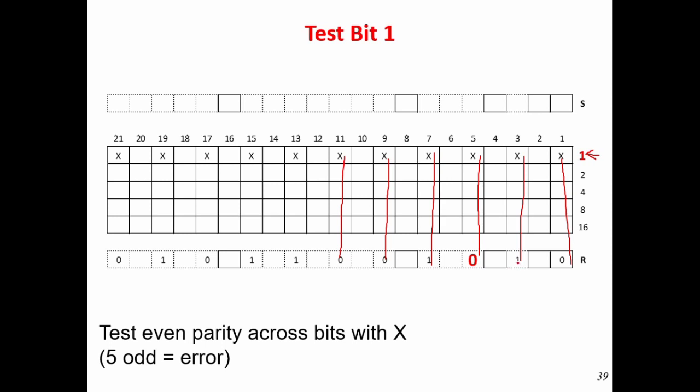And once we see here 1, 2, 3, 4, 5, right? This is 5 ones, means this is odd. And this means there is a red flag here. So there is one problem regarding the first parity bit based on the receiver's counting.